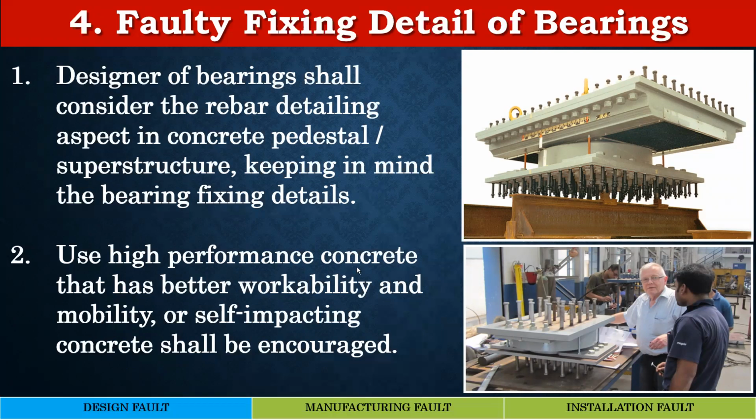So the lesson learned from here is that the designer of the bearing must also ensure that the connection of the bearing to the superstructure and the pedestal duly takes into account the fixing arrangement of the bearing with the superstructure and the pedestal.